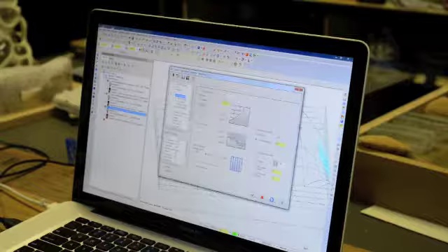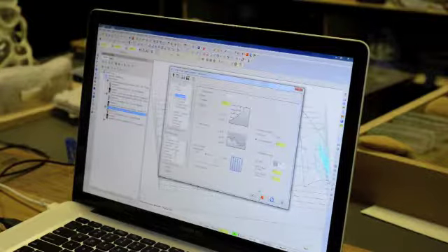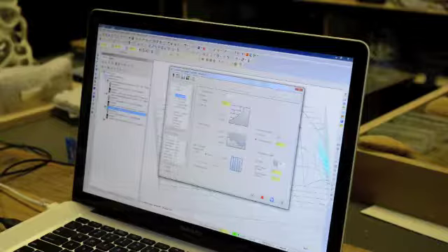So this is hardwood and we have a smaller diameter bit, so maybe prudent to go with a slightly smaller step down instead of, you know, a 1/4 inch or something more aggressive like that. And then we're doing a finished pass, so we don't want to leave any stock on the wall, so that's already defaulted to 0.